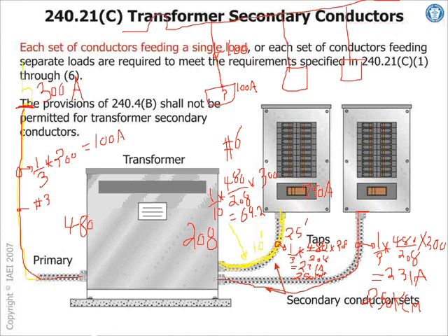So this is another tap also, guys. If you have a transformer here, and here's my conductor coming out of the transformer, and I'm going to tap this, we're outside. Back to the outside. I'm tapping that transformer side. This is my secondary side of a transformer, this area here, and I'm tapping it. How far can I tap the secondary side of the transformer?